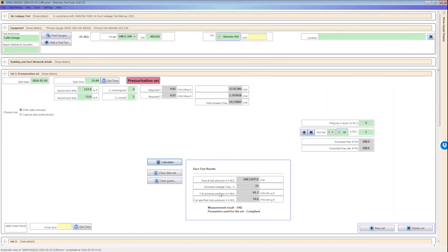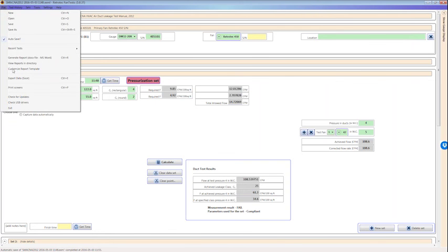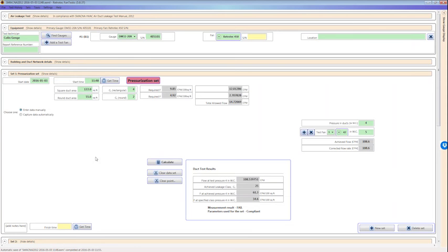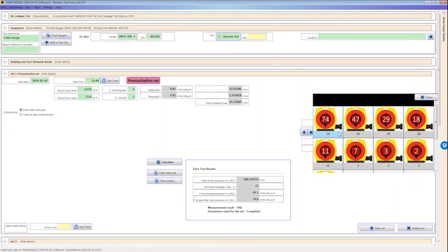The only exception to that is in our 3000, 6000 fan line, you can buy what's called a 4000 fan, which is a 6000 fan that runs backwards with a reverse pitch blade, so they run in what we call the contour mode. You connect two of these fans together, and they will blow 5,000 CFM at 2 inches, but not much above 2 inches.